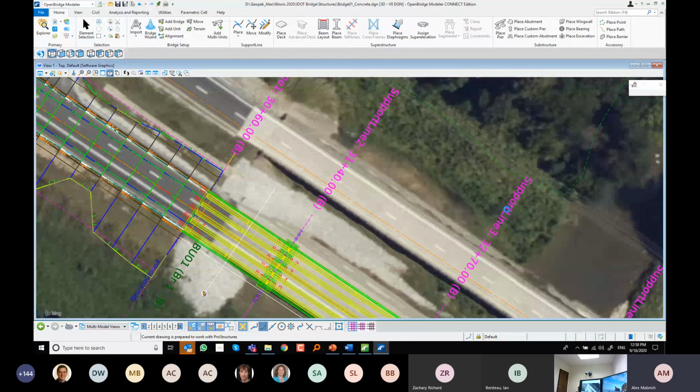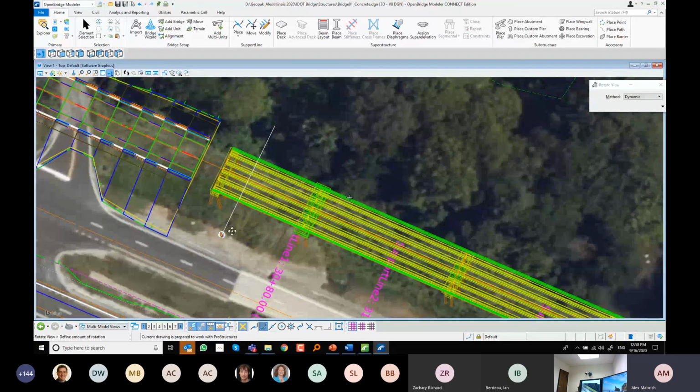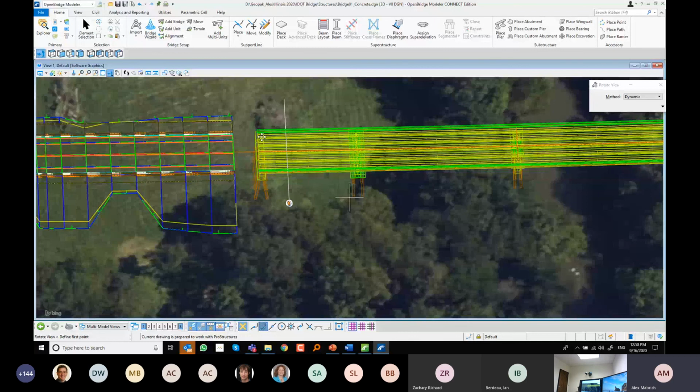So it can do all of that for you, still updating. So it reacts to changes. Again, that's another beauty of all the work being interconnected. And then, of course, as I move the bridge limits, it's reading the new profile information, you see? So now it's shorter because maybe they modified the coordinate. And new quantities are in place, new deck elevations, and so on. And you don't need to do anything else. I mean, the whole abutment adjusted already, and the beam seats and everything else is already adjusted. I can move basically anything I want.